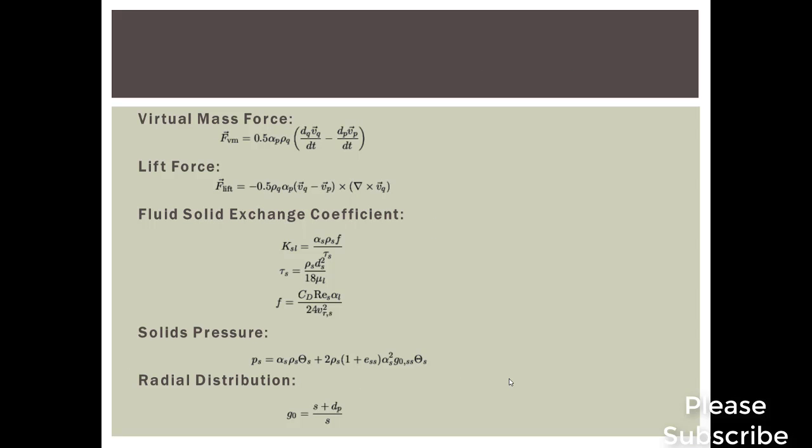So this is the virtual mass force. Virtual mass force comes into action if there is a relative acceleration between the two phases. If there is a huge acceleration between the two phases, this comes into play, or we can take it as zero if there is no huge acceleration. And this is the lift force, which comes into action when the particles are dense in nature and when it is leaving. And this is the fluid-solid exchange coefficient, where there is momentum exchange between the fluid as well as the solid.